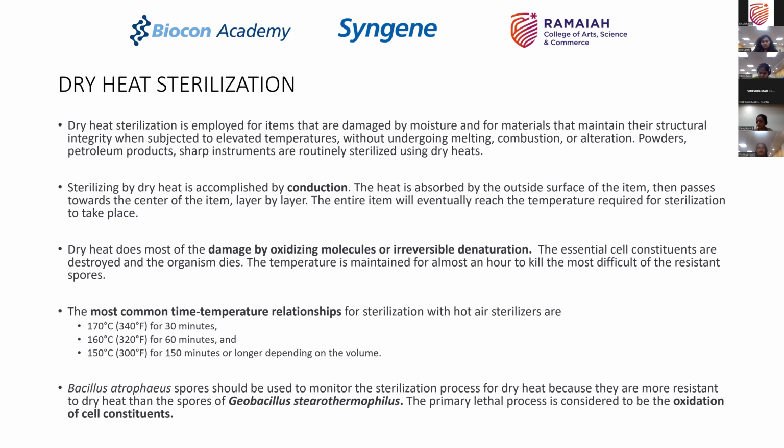We have looked at depyrogenation tunnels where the temperature goes as high as 300 degrees centigrade for a short period of 3 minutes, because there you are looking at the passage of a vial, a cartridge or a PFS into a tunnel on a continuous feed basis. And if you had a very high speed filling line like 200 PFS per minute or 600 vials per minute, then obviously what is important is that you need to go to a higher temperature in a shorter time.